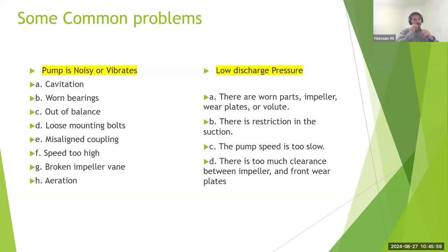Then similarly, selection of the material is very important. If you are pumping an acid which is very corrosive, you would want your impeller to be made from stainless steel or anything which will be suitable for that fluid. If you use simple carbon steel impellers, the acid will wear away the impeller too fast.